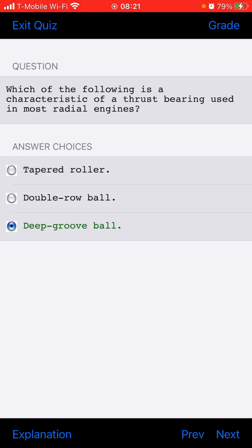How are piston ring gaps installed relative to each other on a piston, and why? Compression ring gaps should be installed in staggered positions around the piston in order to prevent excessive blow-by.